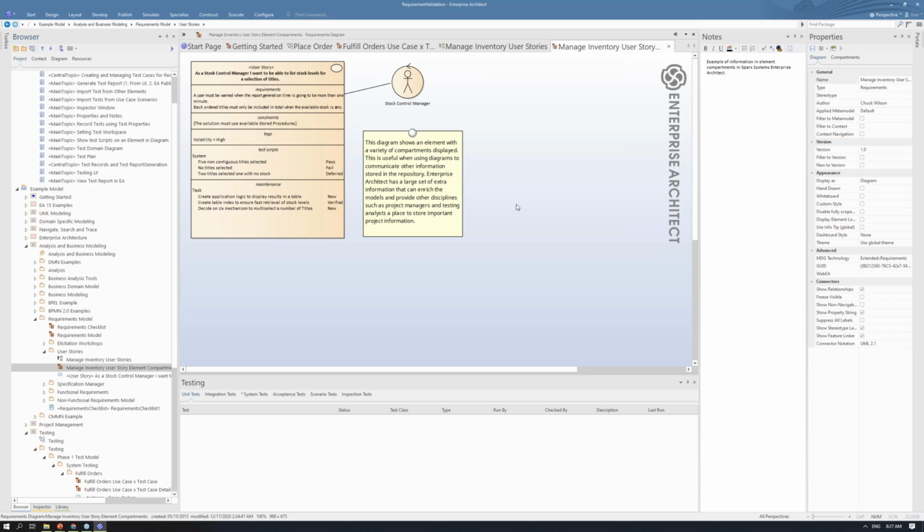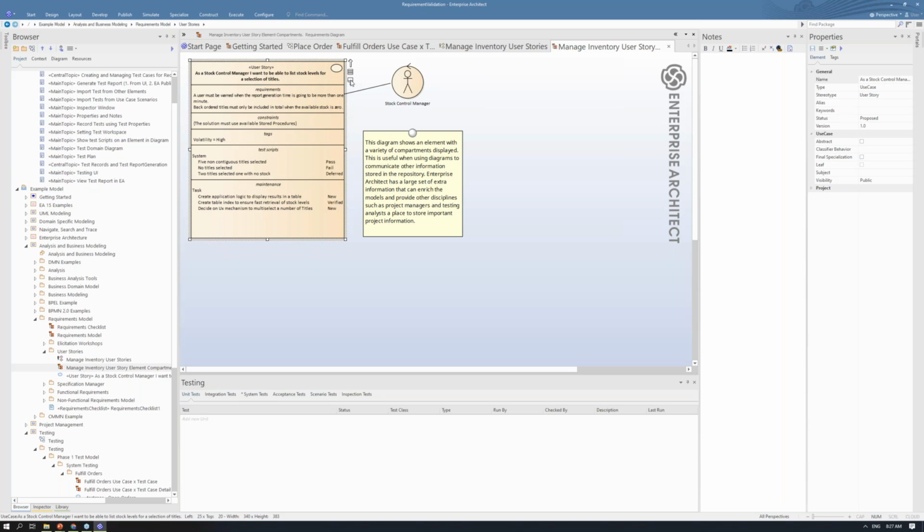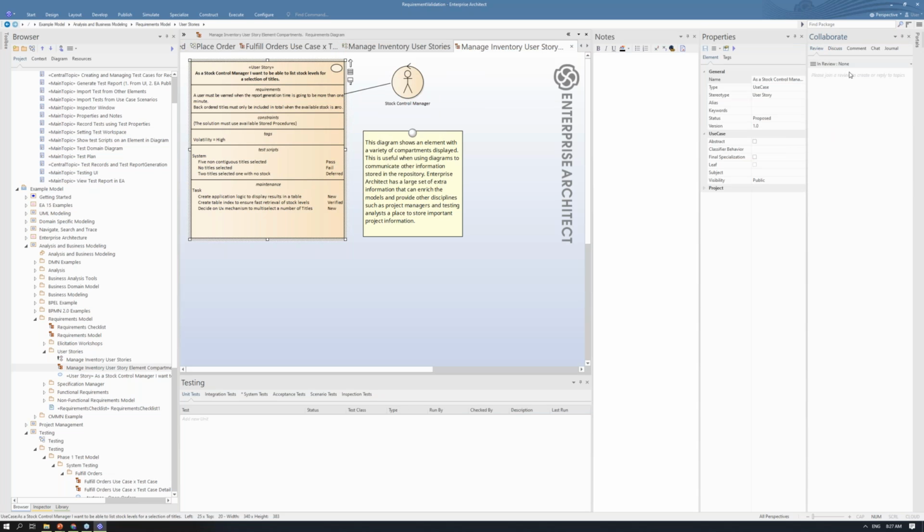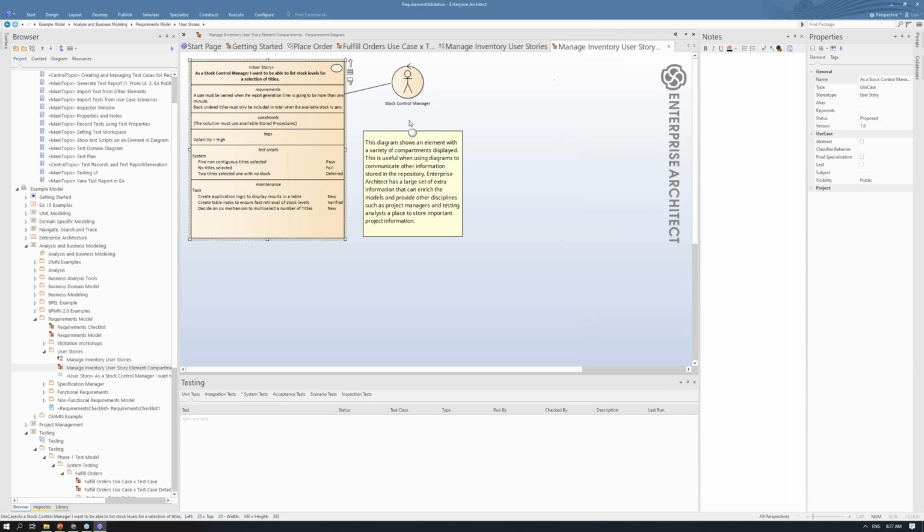Say you want to show this for a verification or a validation purpose to a stakeholder or to a formal reviewer. You just create this and send it. You can just click on this, and EA has very good collaboration features, being improved with every version. So just click on this three hamburger symbol and then say share, or comment, or discuss and review. Send for review. You can join a review and submit it for review to a designated formal reviewer. So this way, they don't have to go into different modes to see all the details.